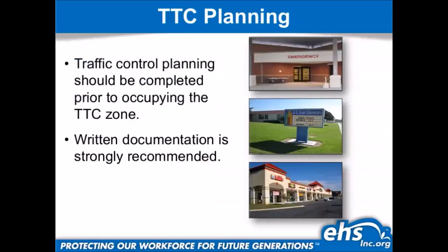Now, traffic control planning, again, has to be completed prior to occupying the TTC zone. Most of the work that's being done, these sites are being visited by these workers maybe multiple times a year. So what should be done is they plan and discuss at the morning meeting and say, hey, this is how the last time we were out here went. These were the issues we had. This is what we needed. This is what we should have each and every time we go out here, right? So the time to discuss these things is while you're still at the yard and not when you're already doing the work. That way you make sure you have everything that you need before you go out there. And again, written documentation is strongly recommended.